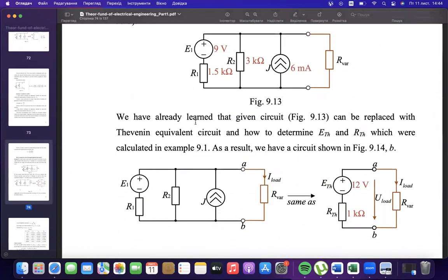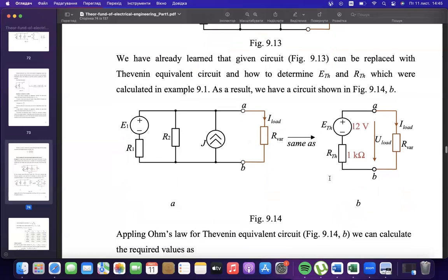Yeah. A couple of examples that we did last time: instead of some circuit with lots of elements, we substituted an equivalent generator of only two elements. Here we substituted 4 elements with 2, but in the same way we could substitute 400 or 4000 elements with a single one. That is why that method is quite comfortable if we are interested only in the right part of the circuit, in some specific branch, a specific consumer.